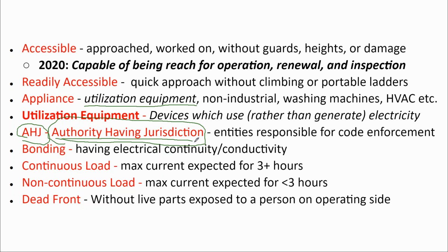One of the main instances that I've come across is in New York City row homes. They can require more robust conduit sizing, a conduit like intermediate or rigid conduit instead of a more flexible EMT conduit, out of concern that these are buildings that could cause a whole lot of fires, not just the one house, but all the houses down the row. So they require it for tall buildings too. They might require better conduit protections.